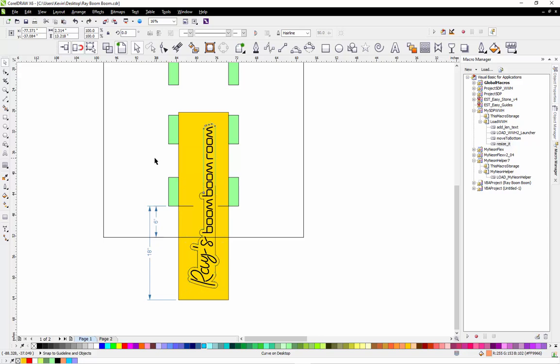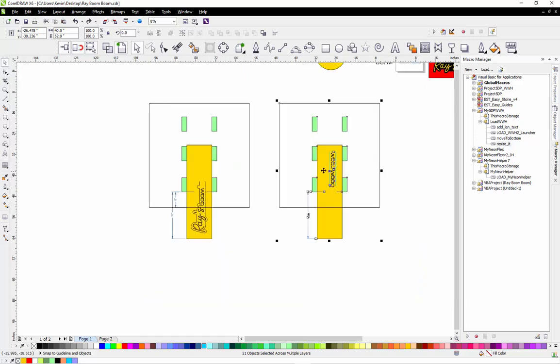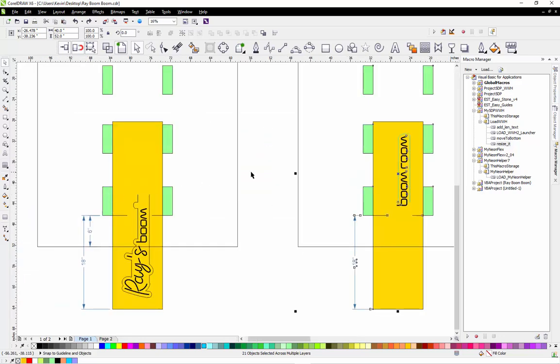So that's how I've got this set up for the 2-inch overlap. I've just drawn a line on my stock so I know how far I have to move it down, and I'm going to line up that line when I do the second part of the cut. It's going to start by doing the pocketing, and then it's going to obviously do the contour. That's how we're going to set it up. That is the process in general.